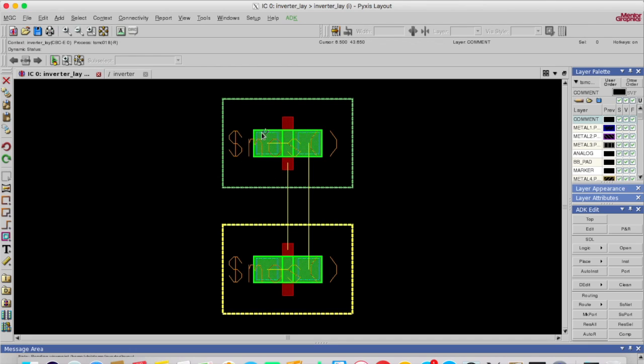As I said, these are interchangeable, but still it is showing some idea how to connect. It is saying to connect these two. This may be source, or this may also be source. If one is source, the other one should be drain. So assume this is drain for PMOS. We have to connect both the drains, so we will use metal to connect them, and we have to connect the gate as well. Poly is gate. We will connect these two together and feed the input through this, and we will also use power rails here, VDD at the top and ground at the bottom.